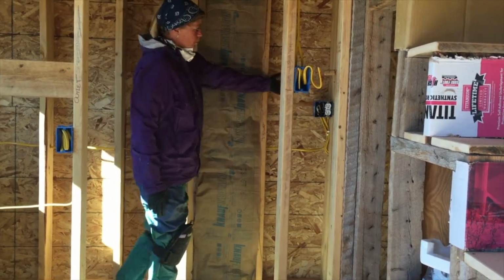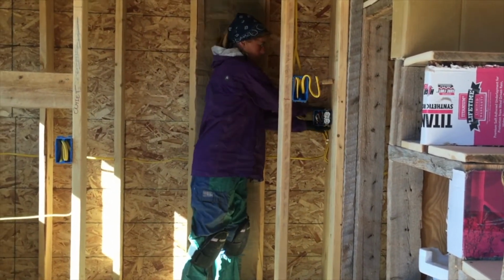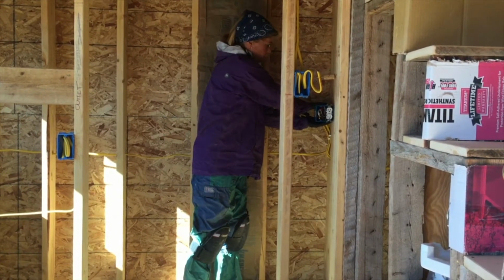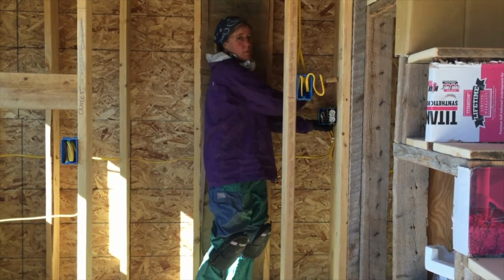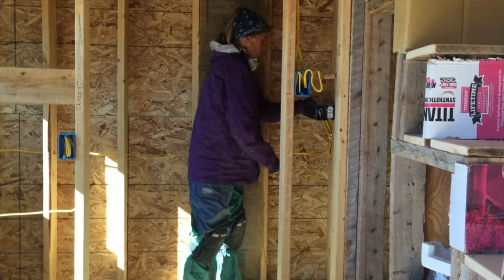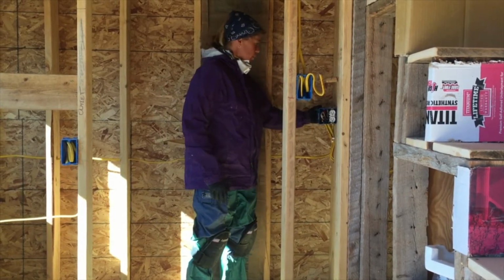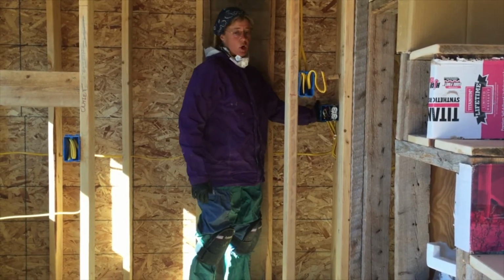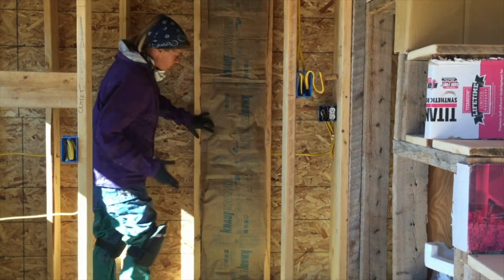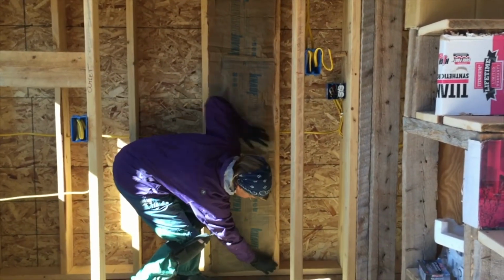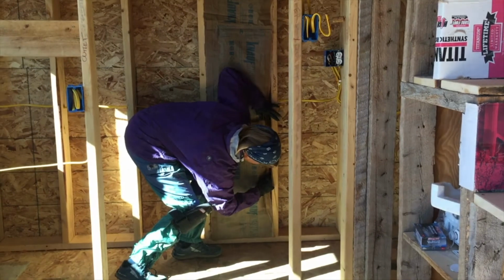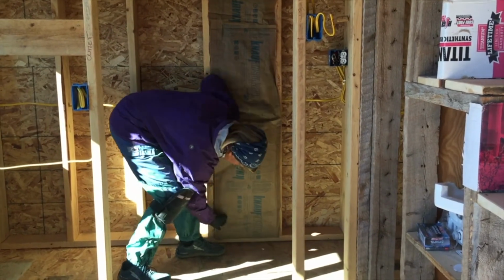We will have a similar problem when we go to do boxes. We will need to cut out a piece of insulation about the size of a box in this front, but we will leave insulation behind to the best of our ability so we don't just have a cold air gap back here. Then once this is in and I like how it fits, I kind of fluff it around a little bit.